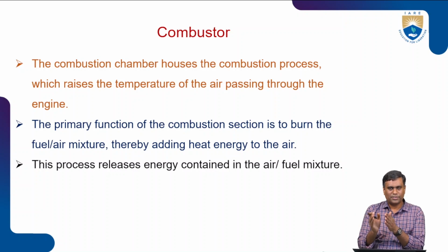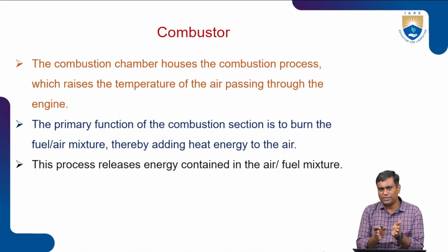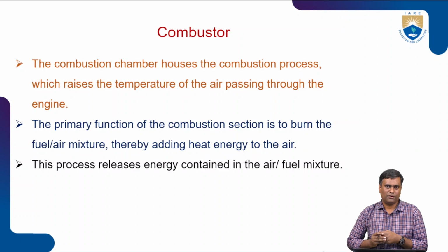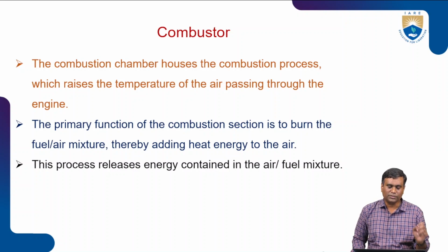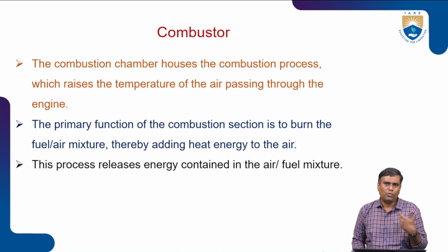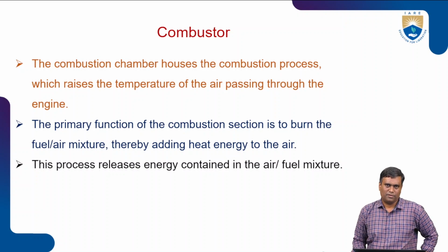That's the reason, because if high velocity, high pressure air enters the combustion chamber, it results in unstable combustion. So for that purpose, a diffuser will be there. And then the role of the combustor is that it houses the combustion process, where the temperature will rise.